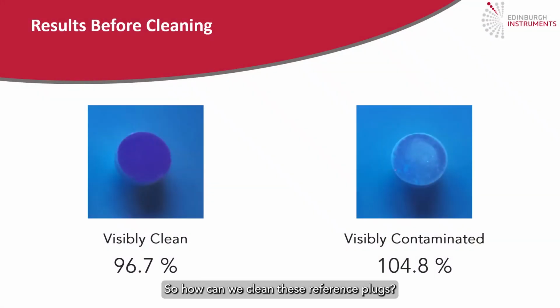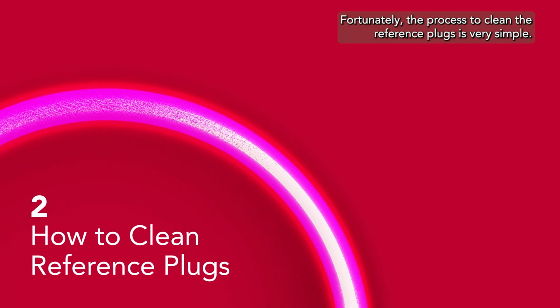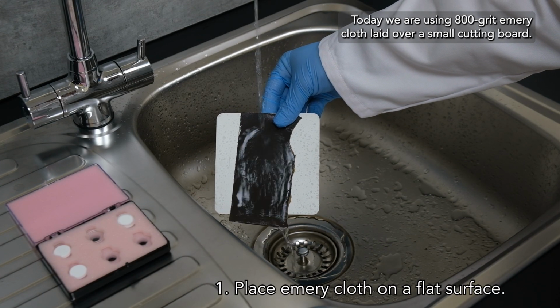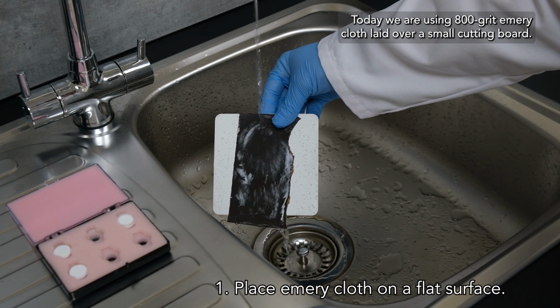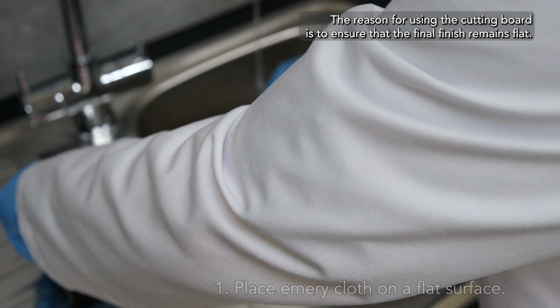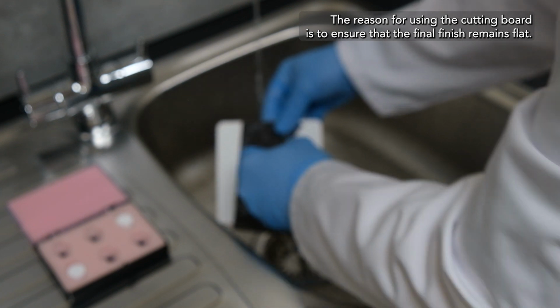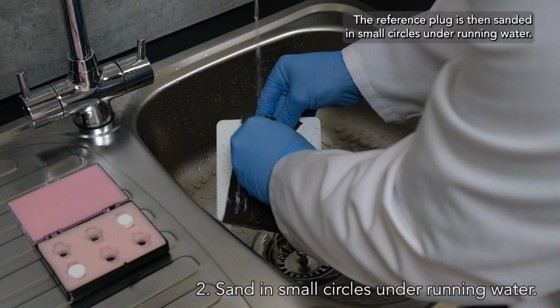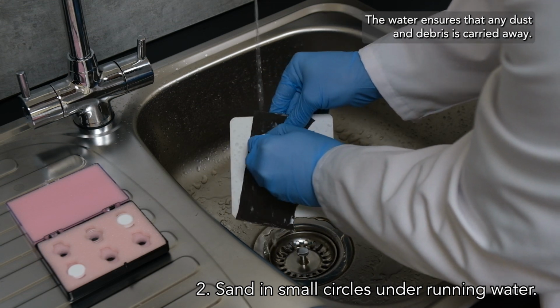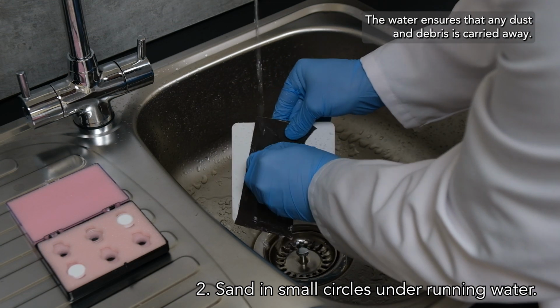So how can we clean these reference plugs? Fortunately, the process to clean the reference plugs is very simple. Today, we are using 800 grit emery cloth laid over a small cutting board. The reason for using the cutting board is to ensure that the final finish remains flat. The reference plug is then sanded in small circles under running water. The water ensures that any dust and debris is carried away.